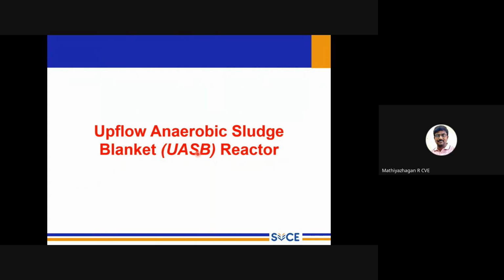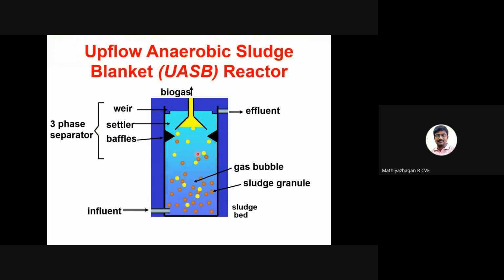I already said we have both aerobic and anaerobic treatments. So far we have seen some of the aerobic treatment. Then we have anaerobic treatment also. One important reactor we are using in some of the industries is the UASB reactor, the upflow anaerobic sludge blanket reactor. We introduce the sewage from the bottom.